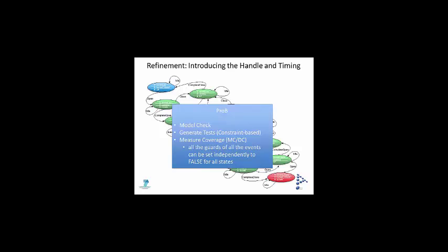And this is effectively a step in the middle. So if you have a gap in your RTL coverage, you can go back to the specification because it's traceable from the implementation to the specification. But then you come to another step to the model. And you say, why haven't I got coverage? If I've got coverage here but not in the implementation, there must be some problem with the specification. So you revisit here and then at the implementation level.